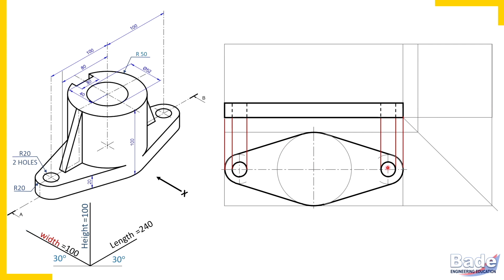But right now initially we are projecting these holes also. So holes, dotted lines in the front view. Now I projected the height of the plate in the side view, 20 millimeters. Check these two red horizontal projectors. And draw end projectors from top view to side view. And this is how you have completed the rectangular block, that is the side view of the plate.